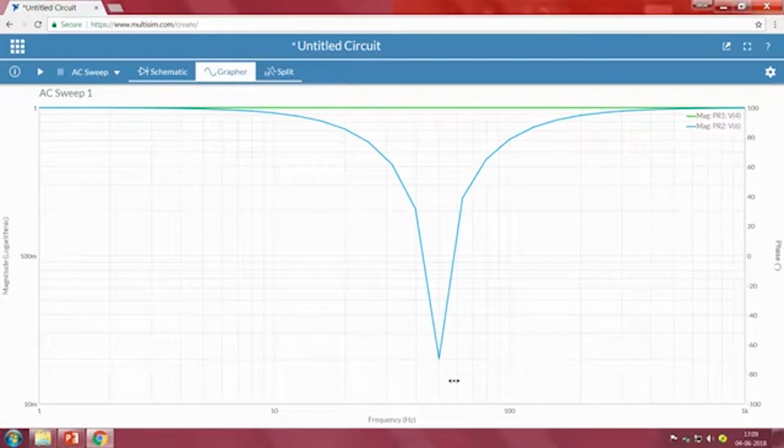So, that is the reason, rather than going with a long range of notch filtering, if we can go with a narrow band of filtering, it would be really advantageous, so that it can remove only the 50 hertz frequency signal. Now, this looks similar to that of our narrow band frequency. Now, how do we understand, since in most cases we may not have a function, we may not have the frequency spectrum to visualize our filter.